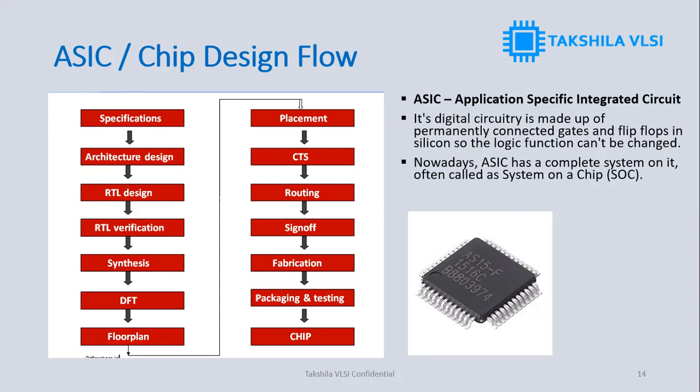So the architecture team will come up with some architecture. That architecture shows the blueprint of the chip. So where a particular module should be present, how many input and output ports, where it should be placed, and what the connections are, buses, registers, flags, everything. So architecture is nothing but the blueprint of the chip. So internal modules, where they should be placed. For each and every module, like analog module or digital module, registers, buses, flags, the RTL code is written.